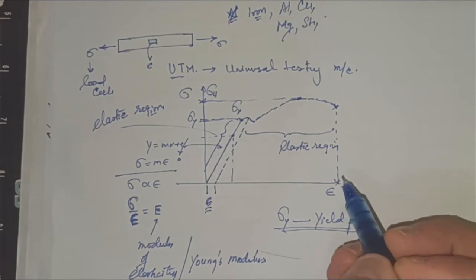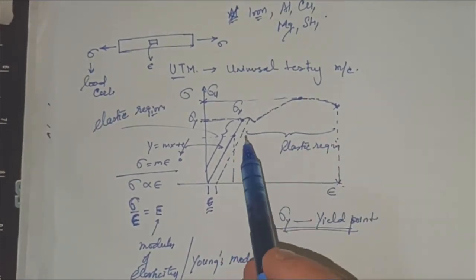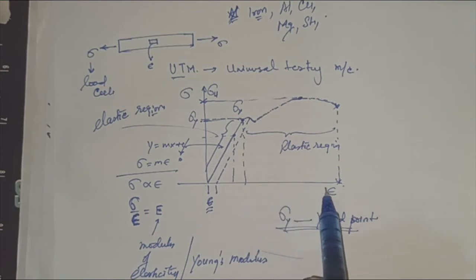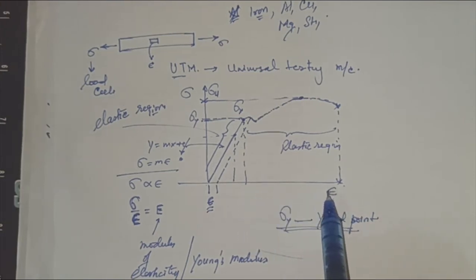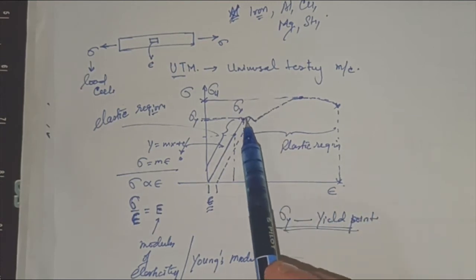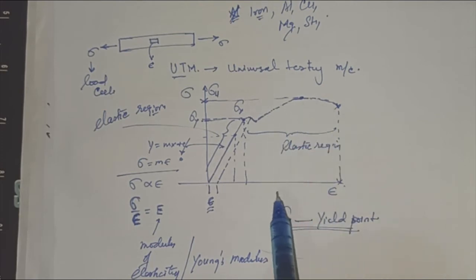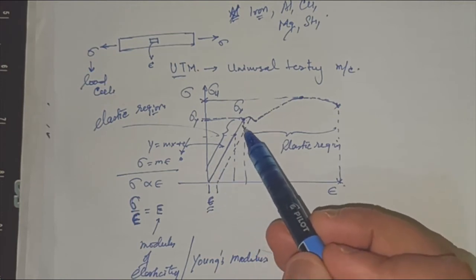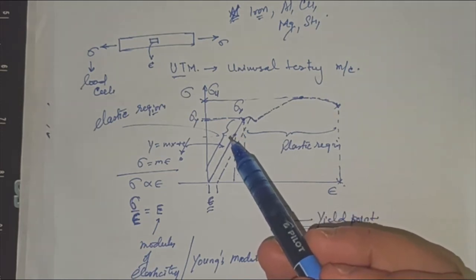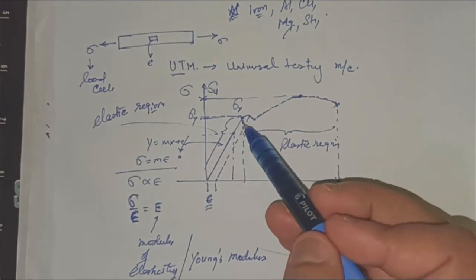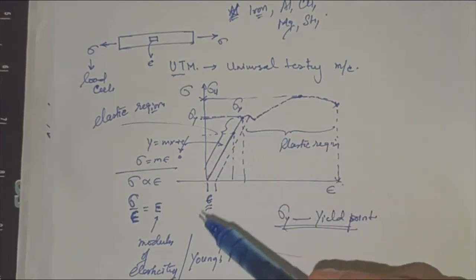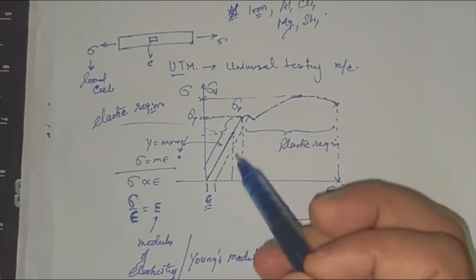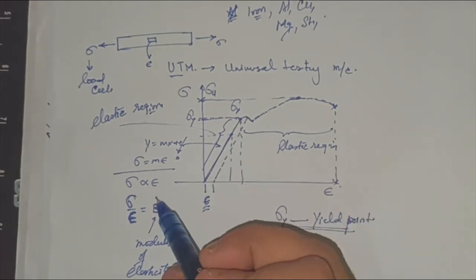At this condition, the material totally fails, and as you can see, after the elastic condition is met, a large amount of plastic strain is accumulating inside the material. That means the material is getting only deformed without any substantial increase in the load. Earlier the material was deforming also, and the material was taking the load also. So in most of the practical or designed conditions, this line is very important to you, beyond which what happens for this course will not be relevant to you. So we'll be talking everything about the elastic conditions only. Within this elastic condition, this curve is valid.